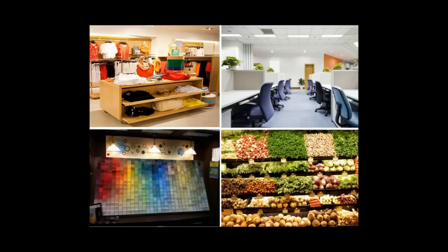If I have an office situation, maybe saturation isn't much of a concern there. Maybe I just need to have a reasonable fidelity value so that things generally look normal. If I'm in something like a paint store or a textile factory where color matching is critical, in that case I would probably want to optimize fidelity and go for as high a value as possible, so that there's constancy in the colors as I'm moving into daylight or an incandescent reference source. I probably wouldn't want to increase saturation in that case, as that is still distorting the colors. Even though I might like it better, it will probably be different when I get it home.